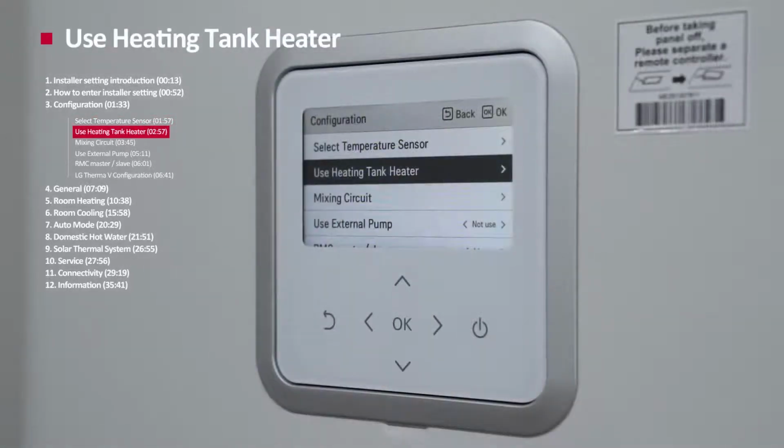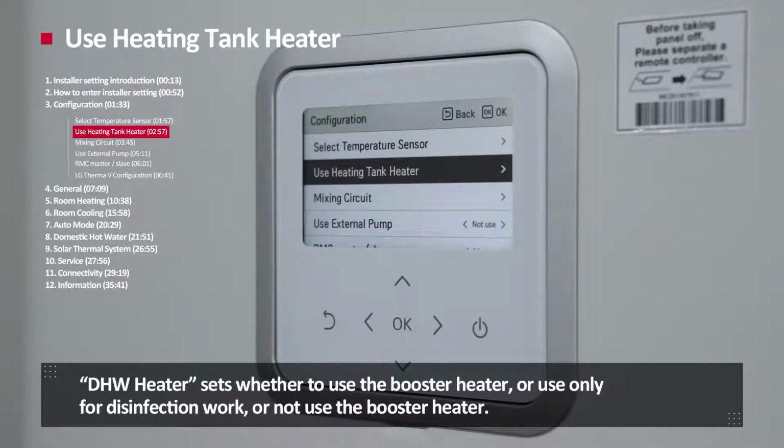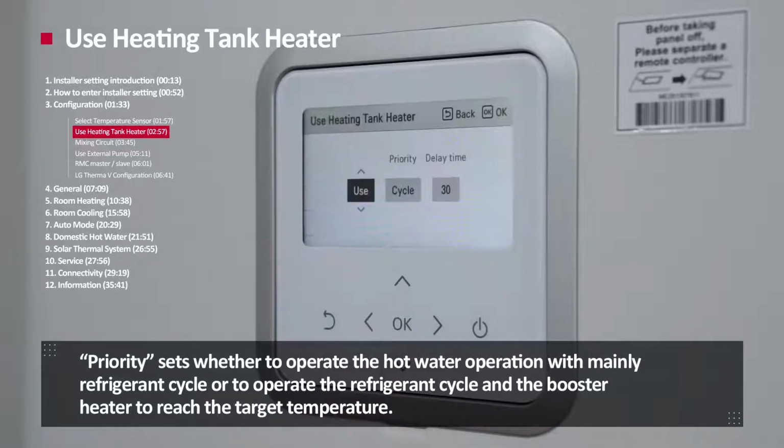Use heating tank heater. Use heating tank heater setting is to determine how to utilize the booster heater for hot water operation. The HW heater sets whether to use the booster heater or use only for disinfection work or not use the booster heater. Priority sets whether to operate the hot water operation with mainly refrigerant cycle or to operate the refrigerant cycle and the booster heater to reach the target temperature.